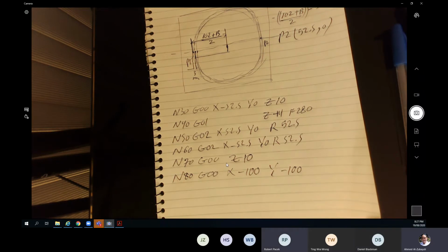Okay, now what's the last operation we need to do? And between the operations, we don't need to restate the absolute dimensioning, right? It's all saved, yeah. By the way, all machines all over the world come by default with millimeter units and absolute dimensioning, unless you set up the G91, which takes it to incremental, and the G20 to take it to inches. So by default, all the machines are using millimeters and absolute dimensioning.